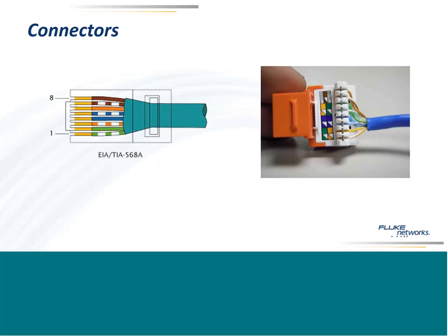Notice those cables, they're not twisted anymore, right? When they come out of the jacket and they go into that plug, they have to get untwisted for a little bit, and even that short little distance, which is much less than an inch, a centimeter or two, they're still in pairs, and there's going to be crosstalk because they're not twisted anymore.